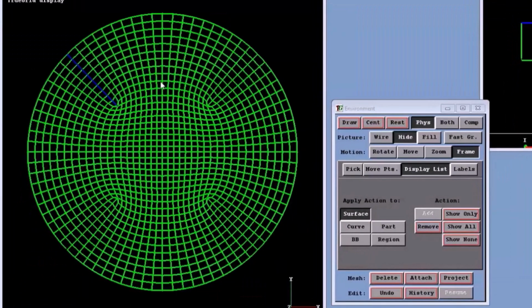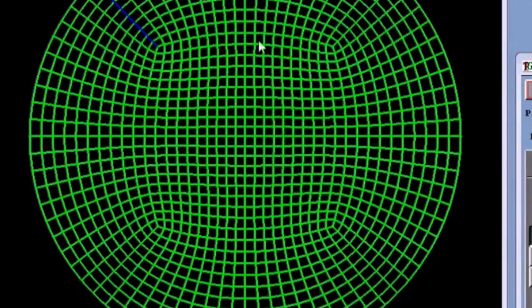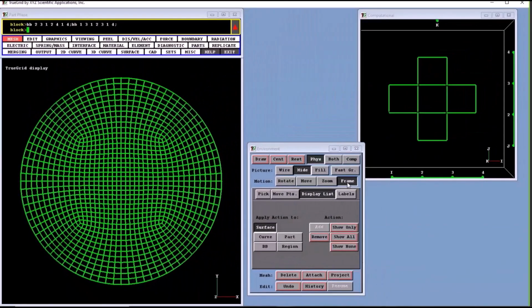Then I tell it to remake the mesh by telling it to draw. And look at the remarkable improvement. And I dare say there's no better mesh for a disk than this method. We have only 4 irregular nodes. And the 3 elements that share those nodes share the 360 degrees as evenly as possible. But let's measure just to be sure.